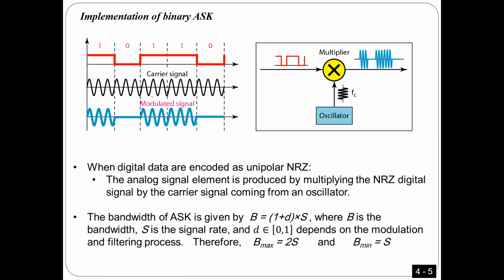As you see here, number one, I need what we call an oscillator. I'm not sure if you have ever heard about an oscillator. An oscillator is an electronic circuit. We use capacitors, we use a crystal, some electronic components. This circuit generates a sine wave with a selected frequency. So you have to select the components of the circuit to generate a sine wave with a certain frequency. That's what we call an oscillator.